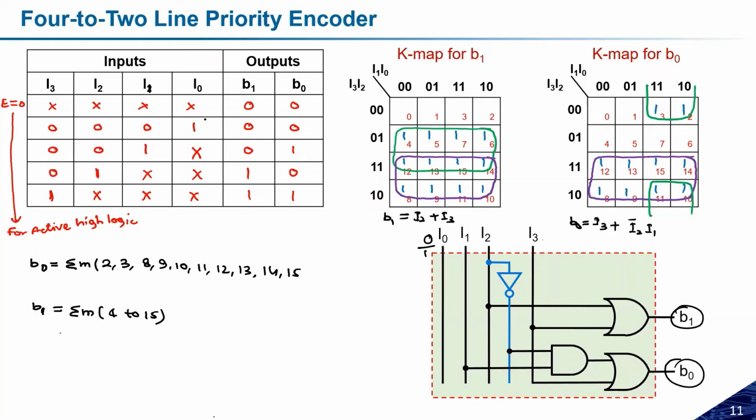So instead of 1, you can keep it as don't care. If you keep it don't care, in both cases you will get 0 0 only. So I0 can be made don't care to get both outputs 0. You got the point of what I said? This is important that you should understand. These are a few things that we should understand.